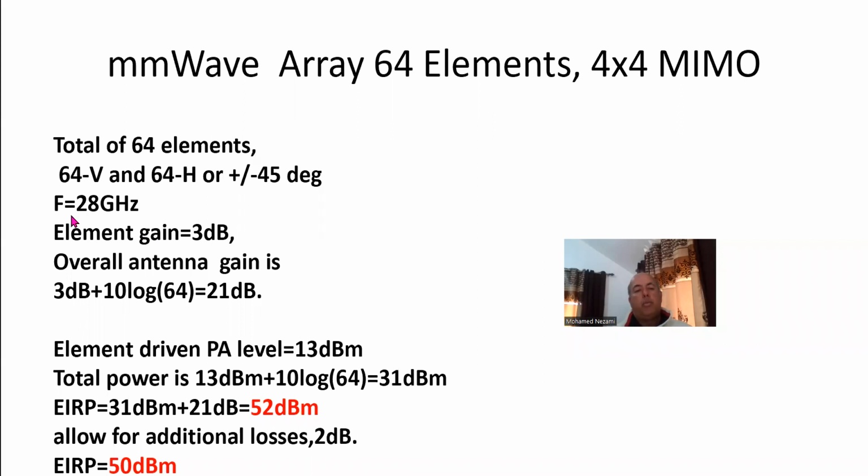Now, even though I'm saying it's center frequency 28 gig, remember, your DAC and your ADC has a huge bandwidth, like 500 megahertz bandwidth, so you can move anywhere in that. You don't have to synthesize your LO to move the frequency up or down from this operating frequency. You could fix that, use a fixed LO, but then move your baseband so that when it comes out of the DAC, it plays it somewhere, anywhere you want, offset it.